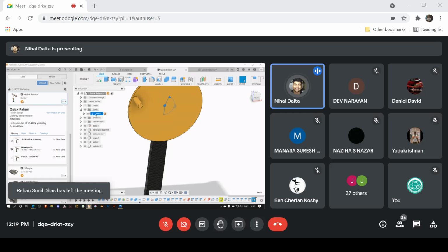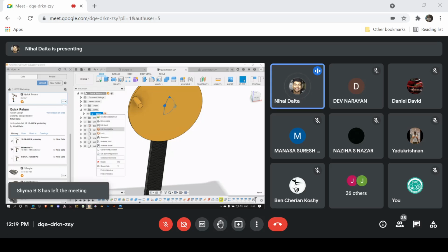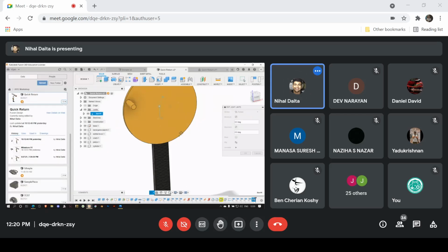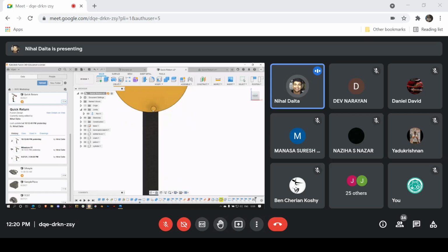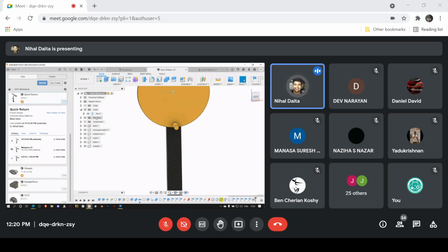If I were to double click, no. Edit joint limits. Okay. So this has a couple of extra options as well, such as lock and edit joint limits. Lock means it just locks it in place. It converts it into a fixed joint. You can unlock it later on. It's fine. So you can edit joint. I want to edit joint limit, right? I just want it to be 0 degrees, if I can manage it. Okay. I guess I have already messed it up a bit. It's fine. I just want it to be centered so I can show you later on. It's fine, I guess. That is 89 degrees. Okay. So the best option would be minimum.